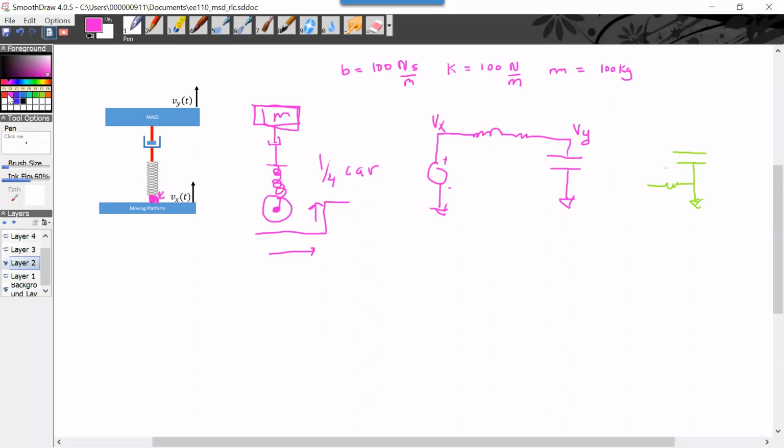All right. A lot of times it's not as important to draw out the waveform as it is to know what kind of waveform you're going to get. Is the system going to be over, under, or critically damped? So let's come up with a system model. This is the inductor, and ZL is going to be SL. ZR is going to equal R, and ZC is 1 over SC.